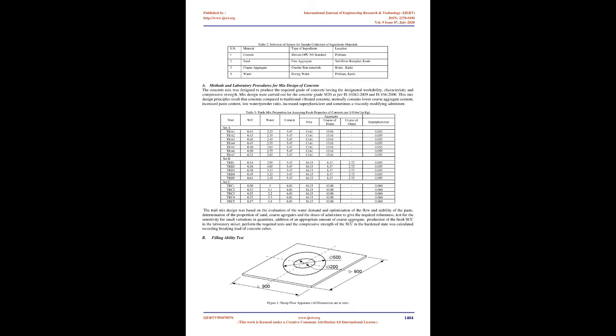3. This study completely relied on experimental work on the properties of the SCC with standard test methods. The properties of the local aggregates, specific gravity, water absorption, and gradation for the mix design of the required concrete grade were determined along with the collection of sampled aggregates. The proportion of concrete ingredients ascertained through mix design was revised through calculation and literature reviews. Necessary ingredients, cement and plasticizer, were accumulated along with rice husk ash.